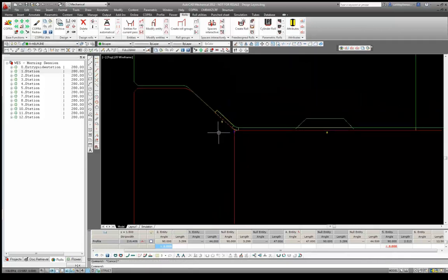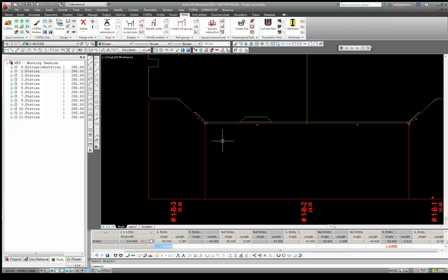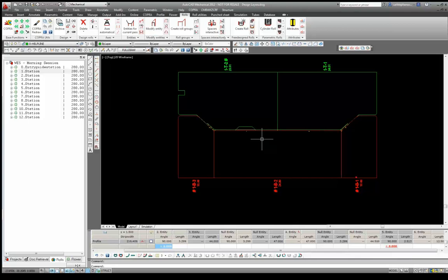What I will do now is go to the Save Roll tool on the Free Design menu and save this roll contour. And then this will also be updated. So there we were able to use an AutoCAD tool to modify the roll contour. But of course it's always important to use the Save Roll function. And then I also use the Save Pass function. So that's free design and classic rolls.